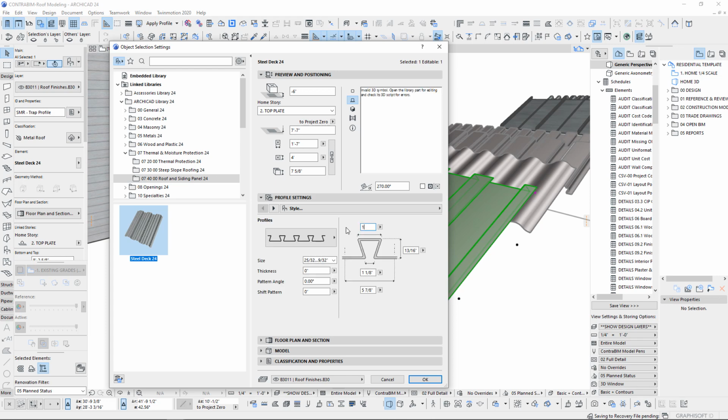Let's see, 1 inch. You'll see that this is an invalid 3D symbol. In this case, it wants us to have this bottom section smaller than the top. So if we go 0.25 inches, 1/4 inch at the bottom, then we can start seeing it come through. We actually have a little bit of a slope on this one right now.